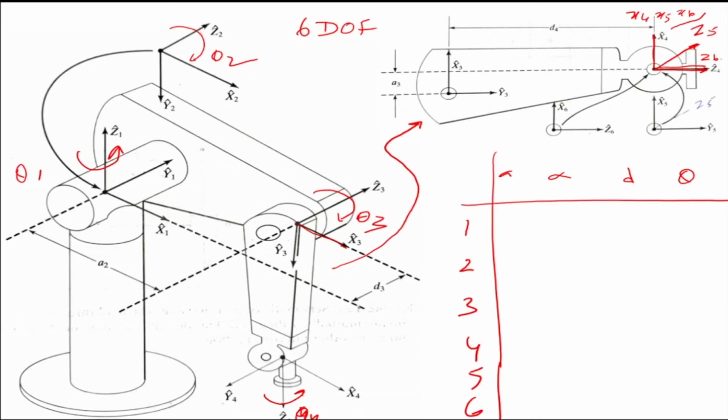Now what we are doing is we are writing our DH parameter table, and our table comes out like this: A, alpha, D, and theta. So the first one, you see the axes are the same, so 0, 0, 0, theta 1. So in most manipulators, theta 1, your first axis and the 0 axis will be the same in terms of frames. Z1 is rotating by 90 degrees about the x-axis, and it's becoming Z2.